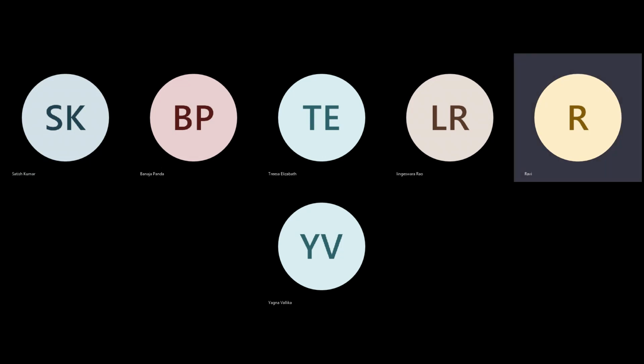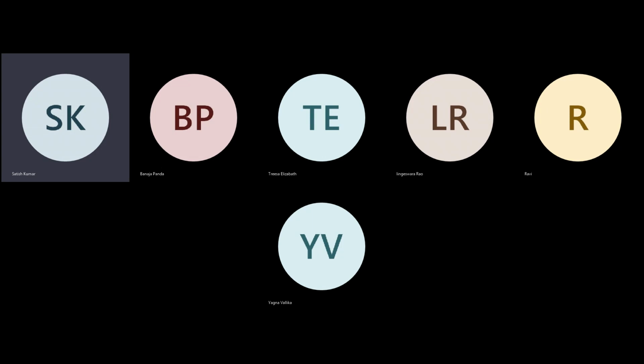Actually, in that question, I thought one more tricky point is asking about the different height of site row. But the main thing is that it depends on, as you told, multi-height cells. The proper way of answering it is depending on the multi-height cells, because the standard cell height will be constant, width will be varied. I mean, width will be constant, height will be varied.